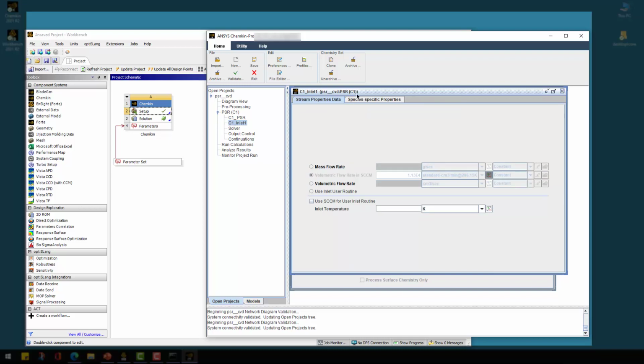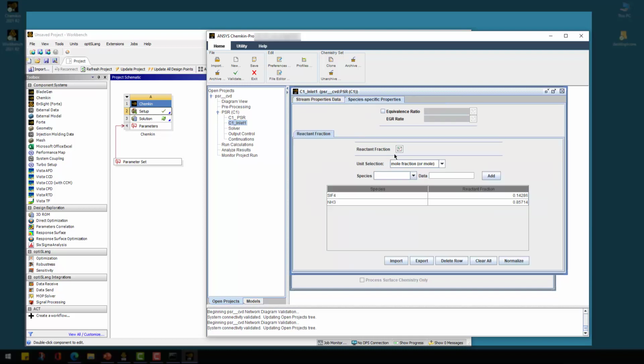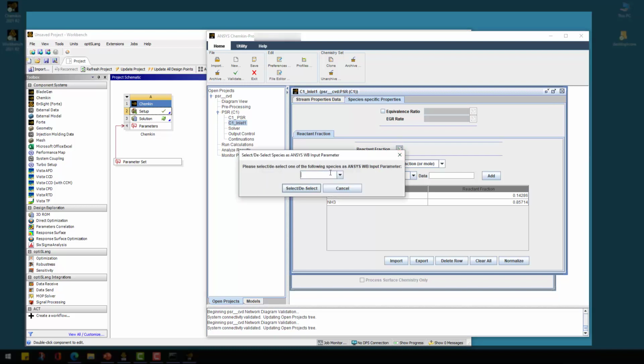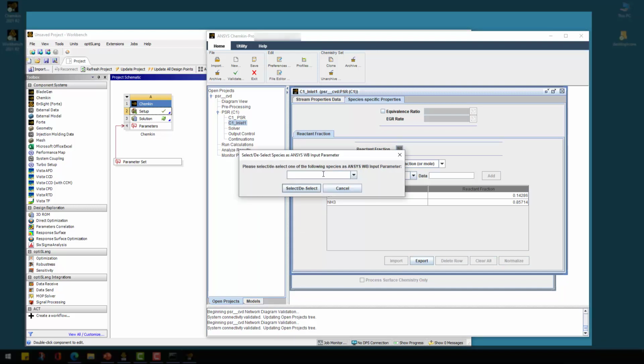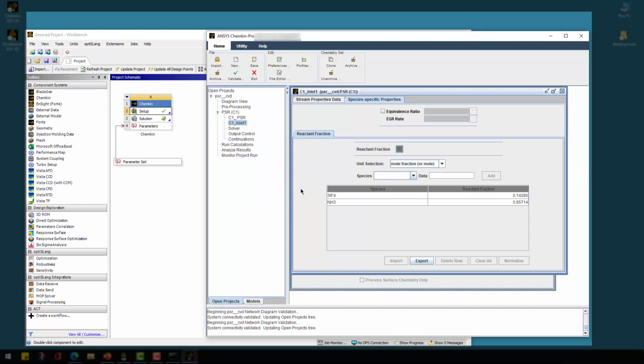The second, I'm going to use flow rate as another control parameter. Same thing, click on this button. I'll use initial or inlet composition as another set of control parameter. So if I click on this one, and I'm going to type in the name of the chemical, it's silicon tetrafluoride, and I'll also use ammonia as composition one.